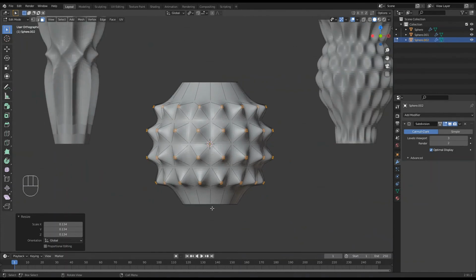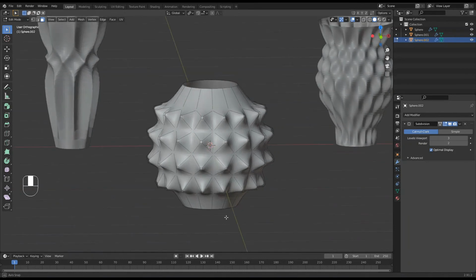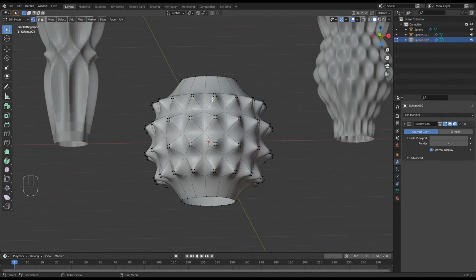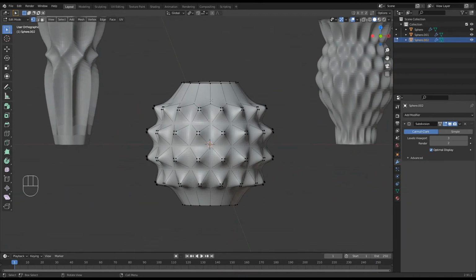And now I'm just going to change the character of, where am I? I'm trying to grab the bottom here to get that whole circle at the bottom. And you can see it's not grabbing. And why is that? I'm still in the face select mode. I need to be in vertex mode. So select the vertices, and now visually this changes a bit. We've got all the little dots. Now if I go Alt left click, I've got everything there.